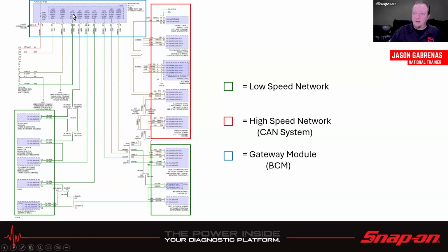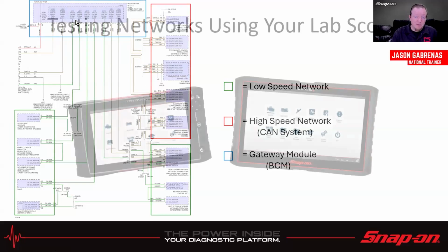And on this particular vehicle, that body control module is the gateway module for this car. So it wasn't translating and allowing out the high-speed information. It was only allowing out the low-speed information. So replace the module, set it up, everything worked as it should. So sometimes communication is not even in the bus itself. It could be in a module itself, such as this body control module.